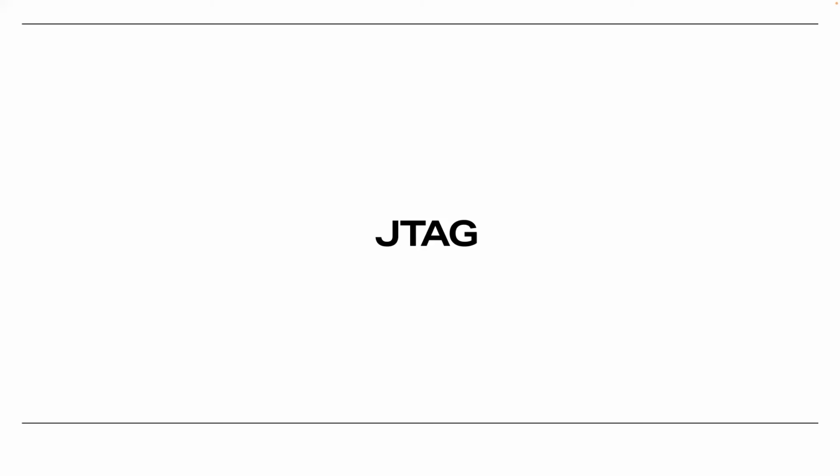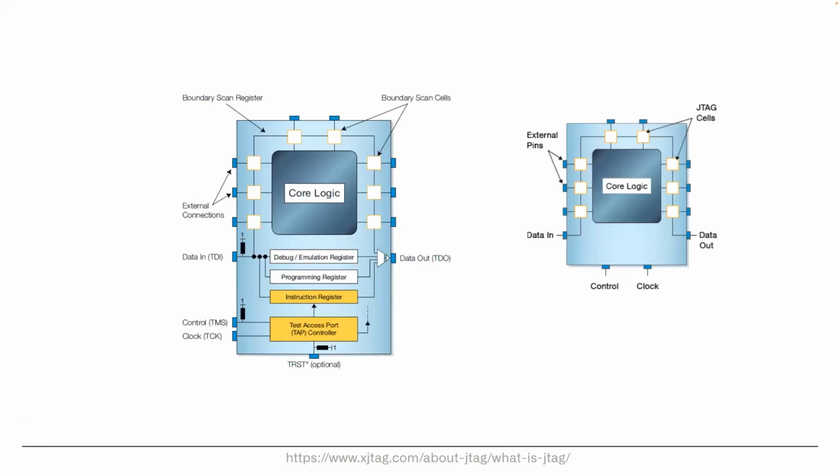So as the device density increased, as more and more chips got added to the device, there was a requirement of a better solution to test whether all the chips are functioning well or not. And that's when JTAG was developed. It adds these boundary scan cells along with each chip, and then these are connected to each other. And in JTAG, we simply send a series of zeros and ones, and we change the state of the TAP controller, which will make the data go in different pathways.